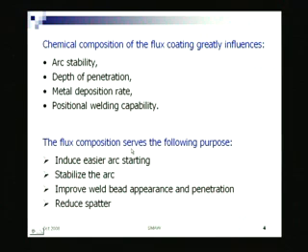So, the first flux composition, what is its purpose? It induces easier arc starting. Induces easier arc starting means what? With a suitable flux composition, you will have favorable gases generated which get ionized more easily, such that the electric arc is initiated very easily. If you recall your workshop practice days, you may recall that many a time you had difficulty initiating the arc, isn't it?